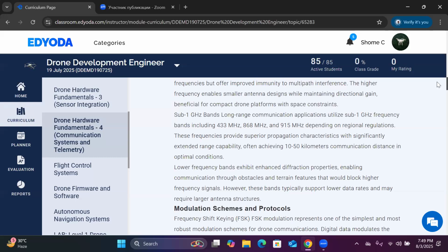I have told you in the beginning, there are two other frequency points apart from the center frequency. If I denote the center frequency by FC, then there are two other frequency points, which are called F1 and F2. What is F1? If we have the bandwidth, then FC minus bandwidth by 2 will be your F1. And FC plus bandwidth by 2 will be your F2. So you need to know the F1 and the F2. The enemy will not be knowing your bandwidth.